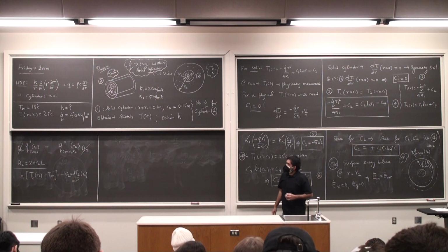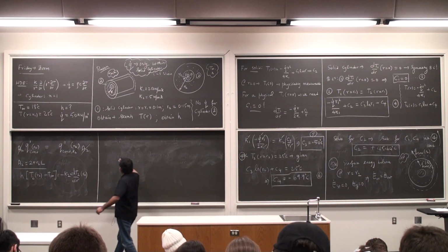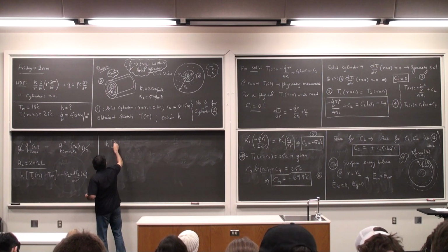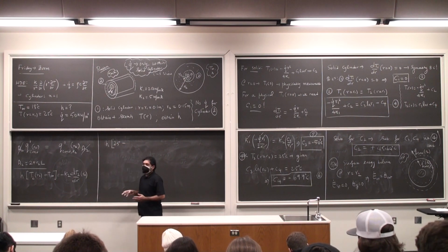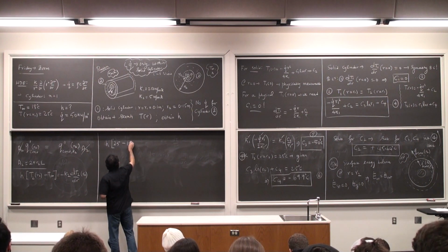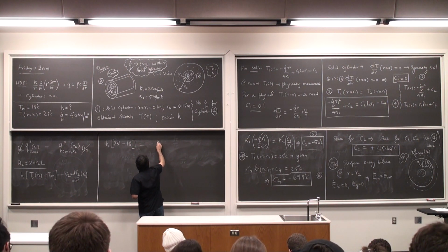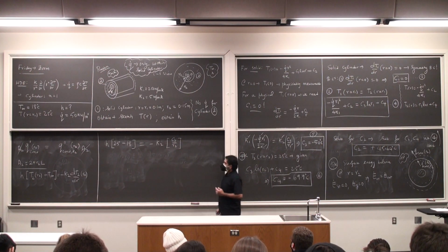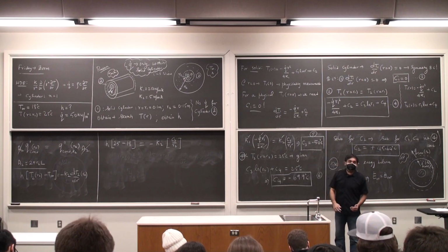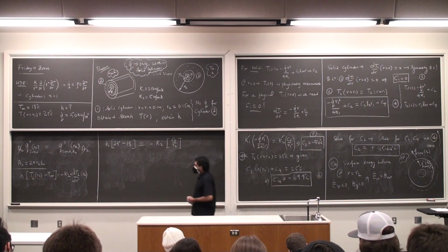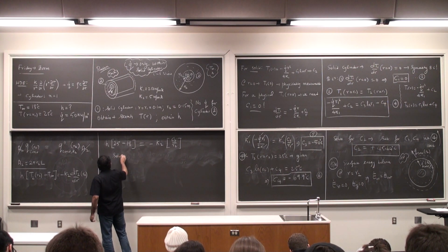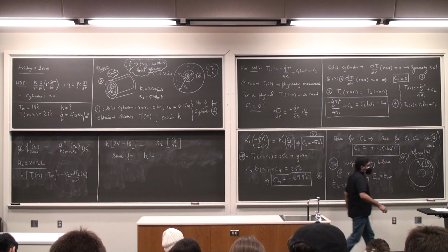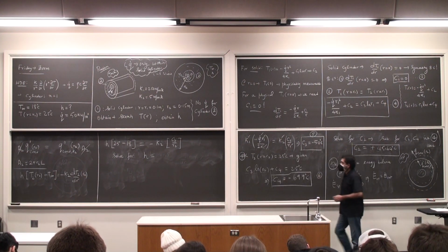Alright, and do the substitution. So h: T2 at R2 is already known to me, so that's 25 degrees. I don't need to go through and do the substitution. T infinity is 18 degrees, that's given to me as well. This is minus K2 C3 by R2, which is the differentiation of the temperature T2. Okay, solve for h. It ends up being 238 something.